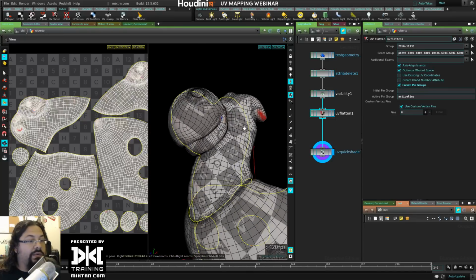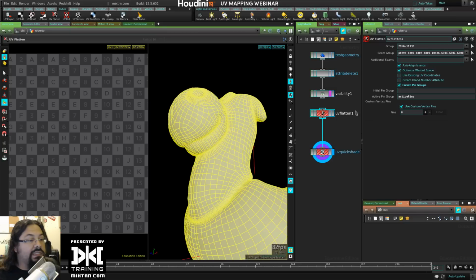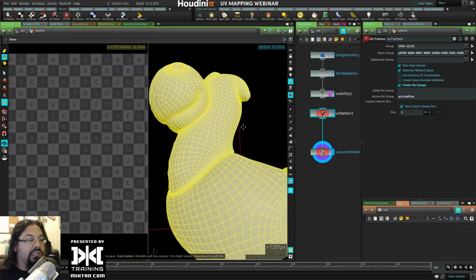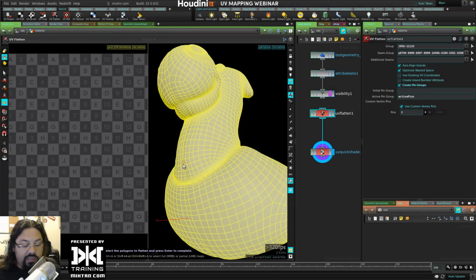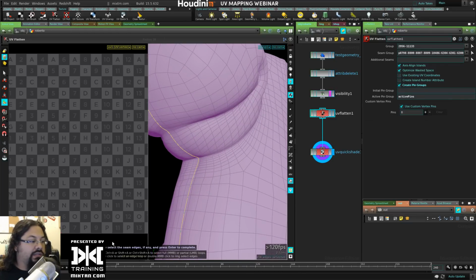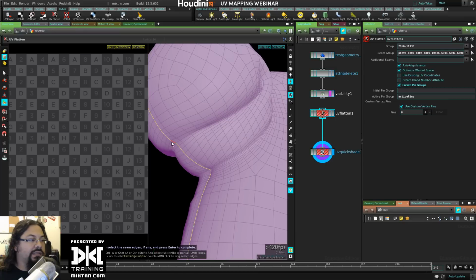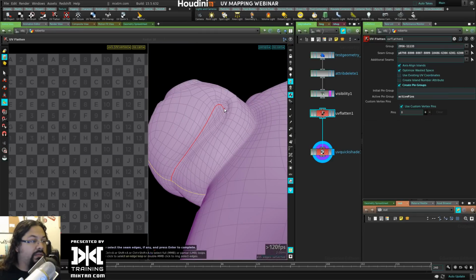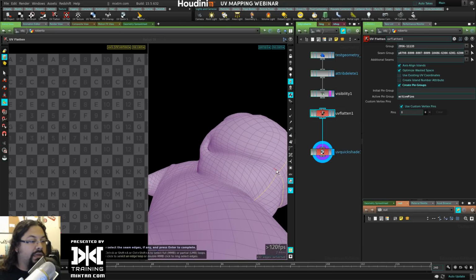So for that, with this selected, I'm gonna press the tilde key, the one just below the escape. Press that and it will give you again the selection mode. So select the polygons, it's everything, and it's saying now select the edges. Well, I'm gonna add to these edges by shift clicking here, Shift A to extend that. Shift A will give me like a range. Gonna go, guessing this area is the one that it's distorting here. We go there, get another one here.